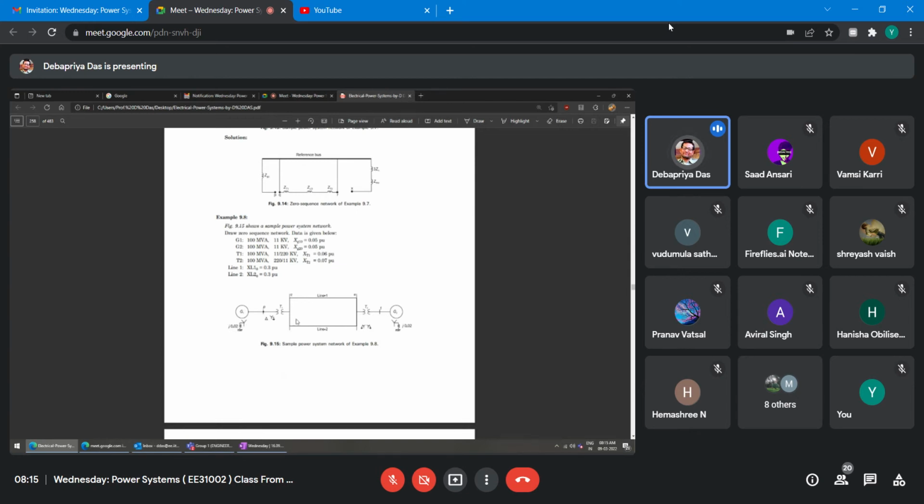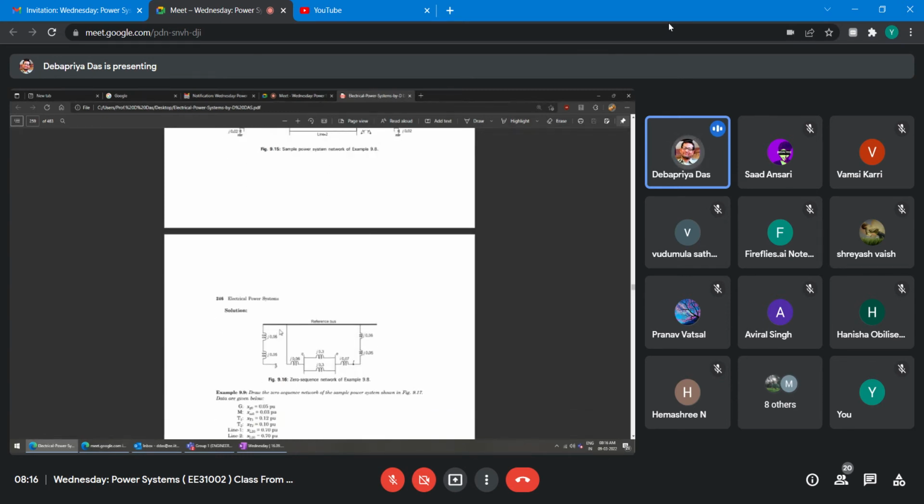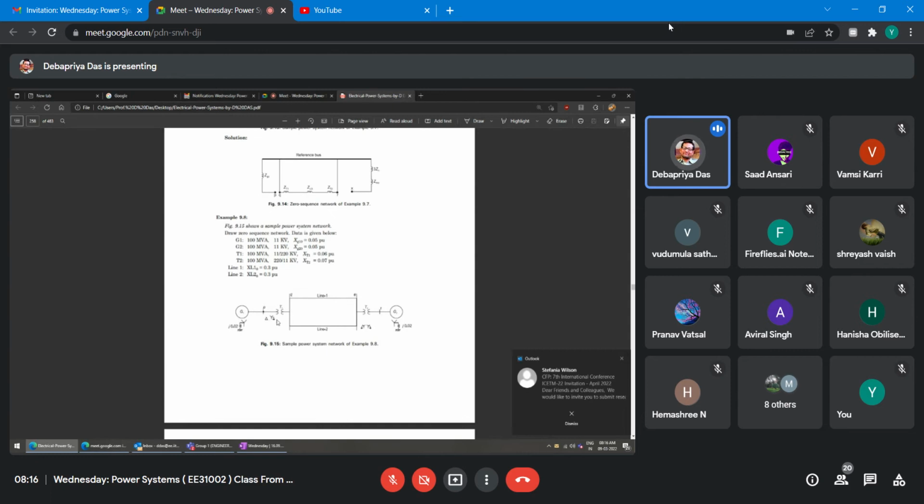here also, you have to see this is star grounded, this is delta. So from this side, when you take the reference line, it will be open, and no current will flow. This is also star grounded, this is star grounded, this is also grounded. So all these things will be connected in series or connected to the reference line. Look at this side, the generator, whose parameters will be computed later. This is 3Zn, then the generator reactance or impedance, we call it impedance. This side will remain open because this is delta. Now star is grounded, here also star-star grounded, here also grounded.